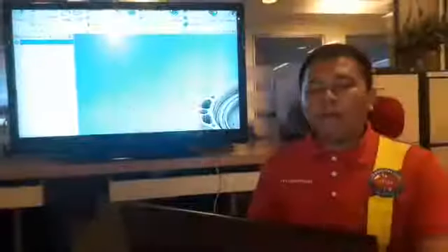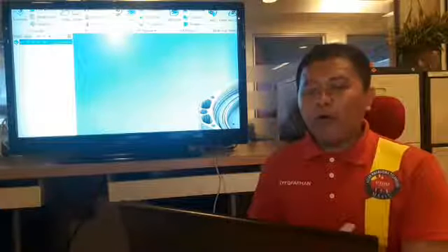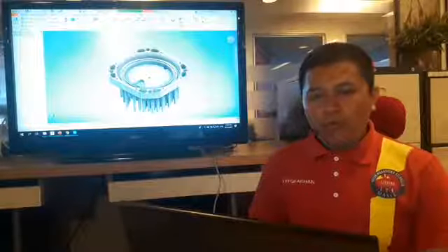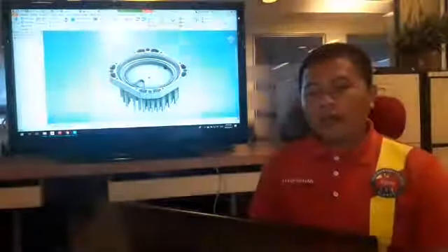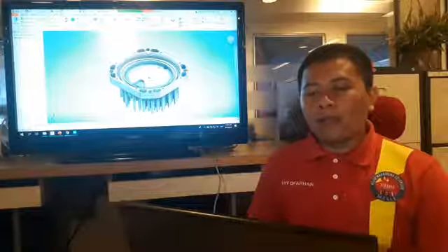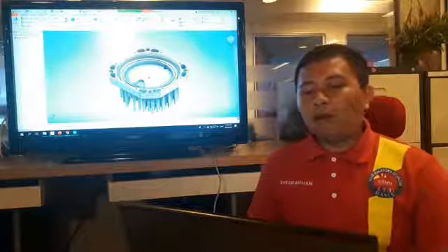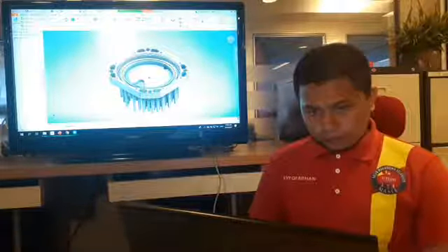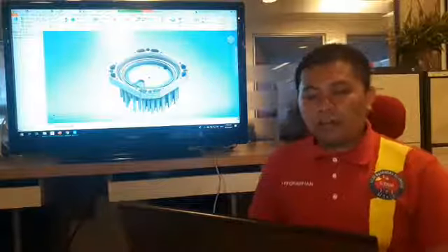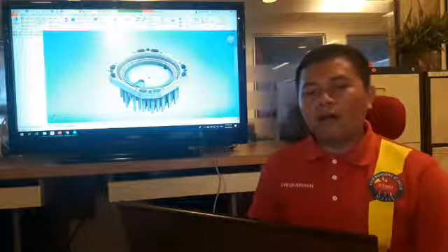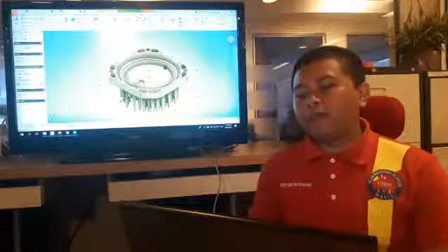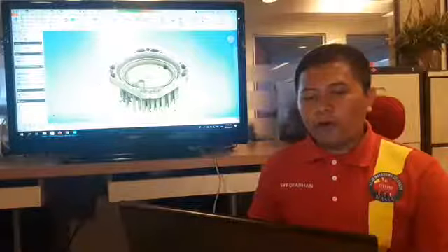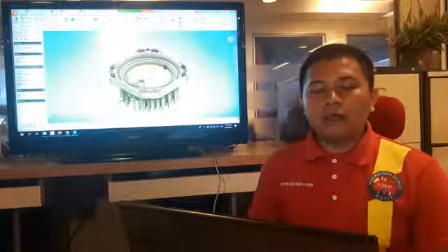If you start from a simple model of your own, for sure your CAM will be empty. For example, you will not have the CAM tab over here. You can go directly to the CAM tab and simply click anything, then the CAM tab will appear. The first thing you need to do is go to Setup. For the setup, you need to make sure of the origin for your coordinates, and another one is the orientation.